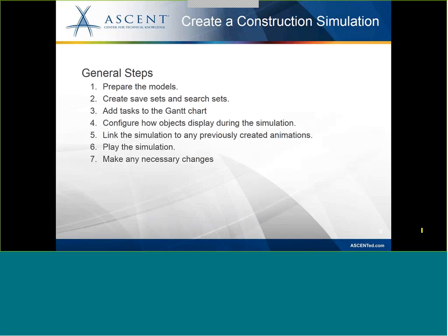Since you are breaking up the models, and by the way, corridor models for civil models are the same idea. In Civil 3D, a corridor model is all one model, or it could be a couple of corridor models in the same model. But rather than putting in your sub-base, then your base material, then your curb and gutter and sidewalks, and very last your asphalt or the concrete wearing course, you'd have to actually separate that out. Like I said, the appendix shows you how to prep that model as well.